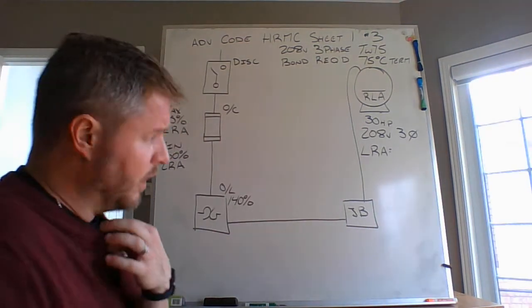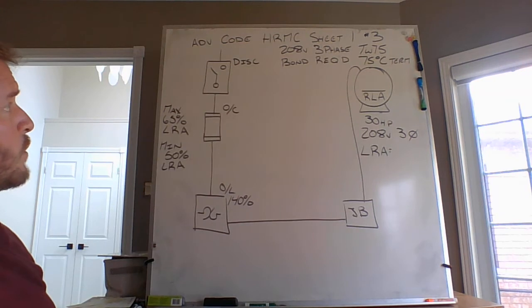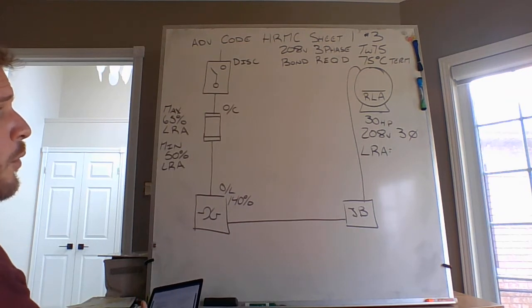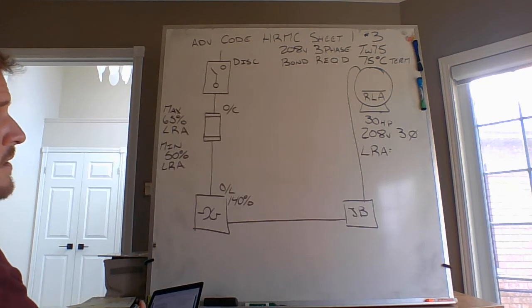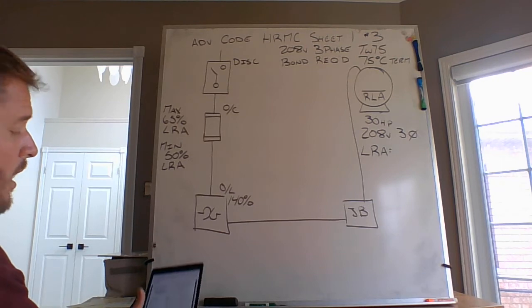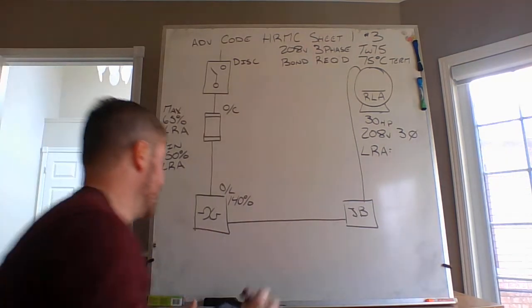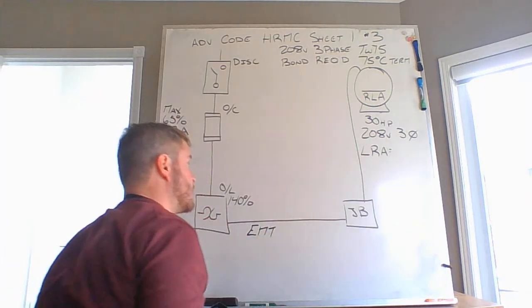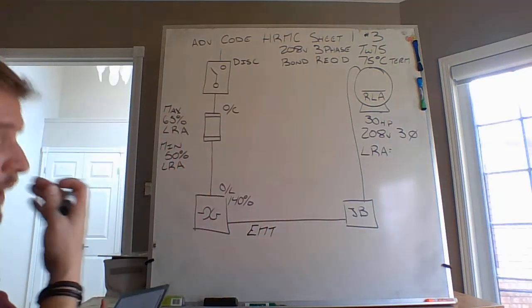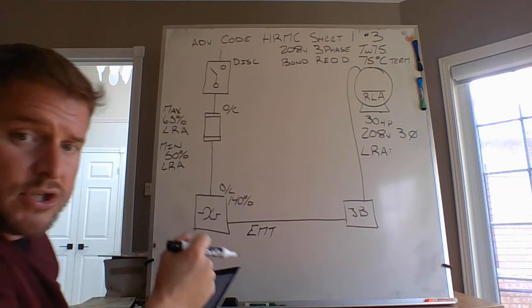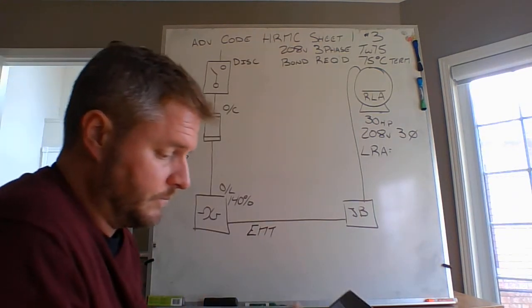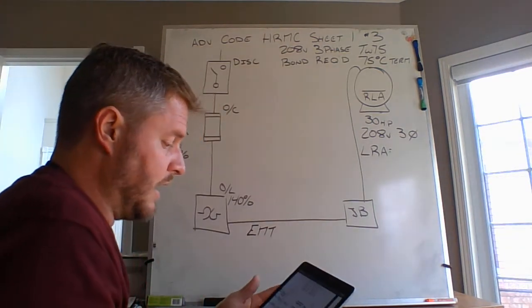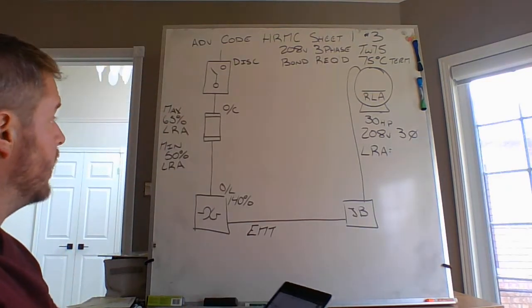In this example, we are looking at this hermetic refrigerant motor compressor from sheet number 1, calculation number 3, 208 volt 3-phase TW75. In this case, we are required to install a bonding conductor. We're looking at EMT as a raceway. And we're at 75 degrees Celsius termination temperatures on everything. Okay? So take a second. You can record these values.